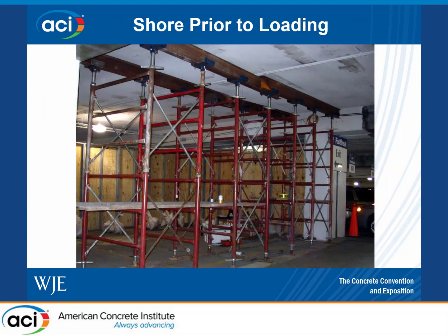Again, you want to install shoring prior to loading, and the shoring should be installed and designed to support both the dead and the test loads in the event of an unexpected failure, unless you're using hydraulics like we talked about before. The shoring should also be installed with adequate clearance to allow for deflections, so you don't want to impact the ability of the structure to deflect during the test. You can tell by this setup, this was just an individual location that we're shoring, but in some cases you're shoring through multiple levels and large areas, so it can be significant expense.